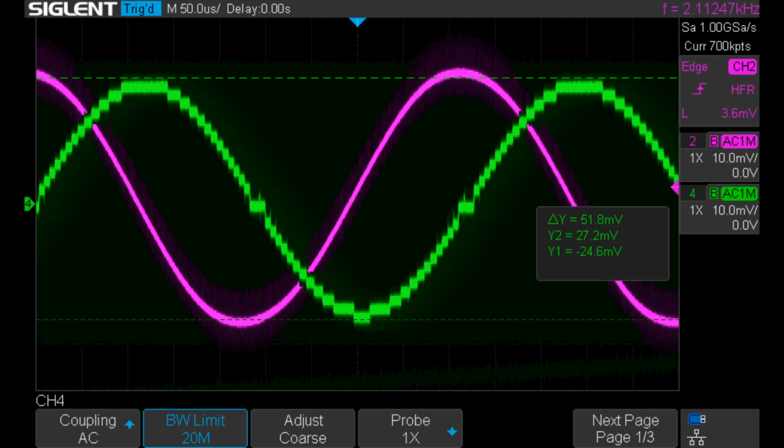In fact, in the previous video, you could see when they happened to line up in time, they were nearly identical. The big difference is that the M2K signal generator is using a digital to analog converter, so it's only capable of producing certain discrete voltages. I believe it's a 12-bit DAC, so it should be able to produce 4096 voltages. And I think we're seeing the effect of that here. The M2K signal looks jagged compared to the one from the Wien bridge.